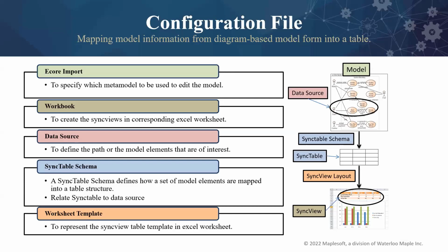In addition to that, you can also control the arrangement of the columns. Let's take the example of the functional decomposition we'll be seeing today. I'll say display level 1 function in one column, level 2 function in the second column, level 3 function in the third column, description probably in the last column, and so on. So this arrangement is also controlled by the worksheet template.